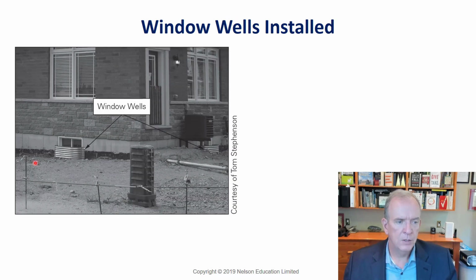So some examples here, you can see the windows. These are partly above, mostly above ground, but the bottom of them will be below ground. And this isn't finished grading. This is the exterior drainage layer, this black here. And this will be graded away from the property. And so this is a protection around the window. You can see another one that's placed over here.